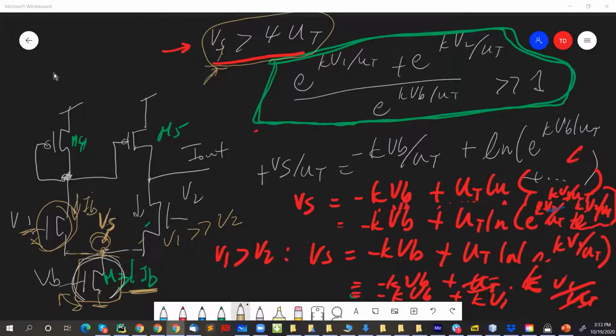When we were talking about the common mode input voltage, which is equal to, terrible handwriting right now, V1 plus V2 over 2, if this common mode voltage is not put in the proper place, then this transistor is not in saturation, and then your transconductance amplifier circuit won't work well. That's why it's important to know where it is. Okay, everything good? So now we go to the output transistors.